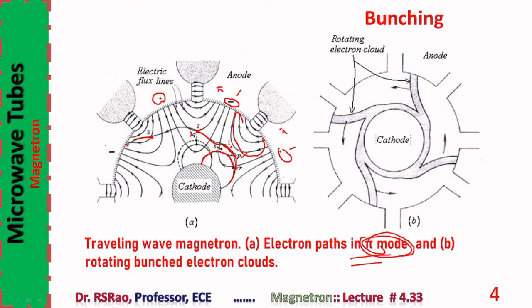Giving energy to the RF field is a continuous process. The journey of the electron is continuous. The rotation of the field is continuous. The interaction between them is continuous. Acceleration by DC is continuous, and energy transfer to RF is also continuous. Of course, for the explanation's sake, we consider 3 points. But in reality, transfer is continuous. From DC to AC, transfer happens in a continuous manner.